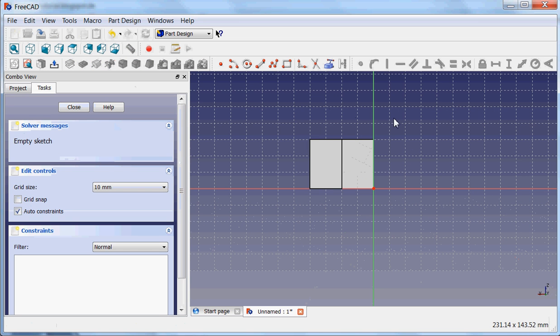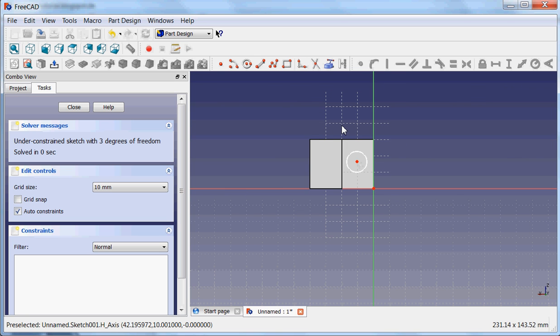And then FreeCAD will turn your model in such a way that you look straight onto the sketch, and to not get confused which is the sketch plane and the higher part, as you see here, the grid lines going over this face, but here there are no grid lines. So we are going to draw in this area by putting a circle over here. Again, the sizes don't matter too much now, and we want to position it from this point, for example.